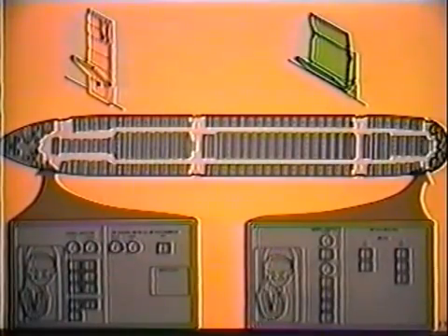A single seat is located at each passenger door, shown in amber. Double seats, shown in green, are located at the center and aft cross aisles. Flight attendant control panels are located at the L1 and L4 doors. They contain the lighting, PA, entertainment, and electrical controls for the cabin.